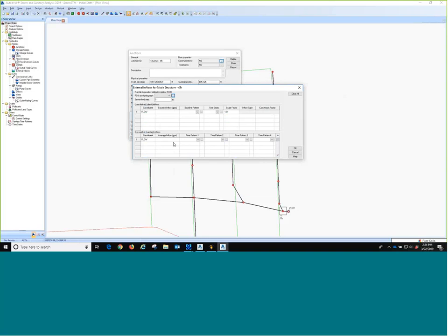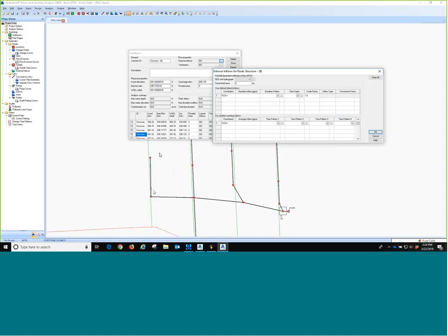In this case, I'm just going to worry about my dry weather flow. So I looked at this area, and I think I had like 10 houses or so. I can't remember how many houses there were per node. I divided that out by 100 gallons per capita per day, or some standard estimate, and I came up with a flow of 1.74 gallons per minute on average.